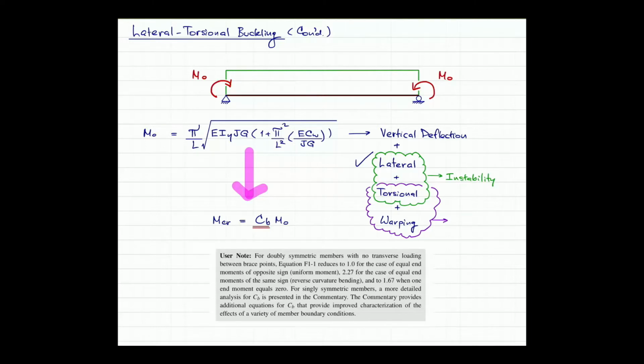Okay, so lateral displacement comes in, and torsional deformation also comes in, as the top and the bottom of the beam will not displace equally, so the torsion is coming in. Then this torsion and lateral, they are actually coming in a package. They come together, and we use the lateral and torsional deformation and the governing equation for these two to cast for the instability of the beam.